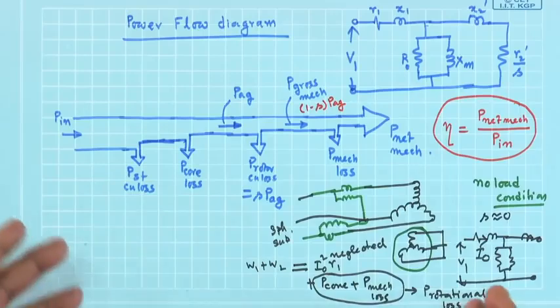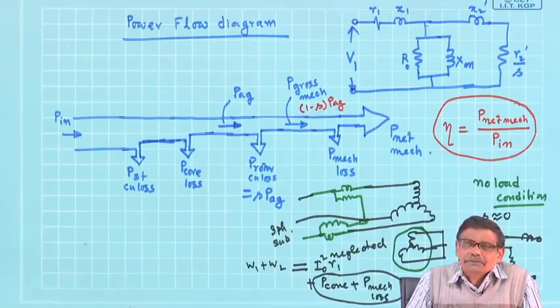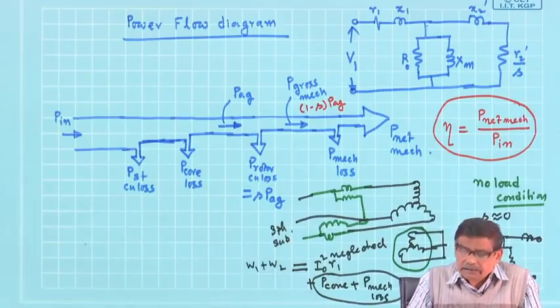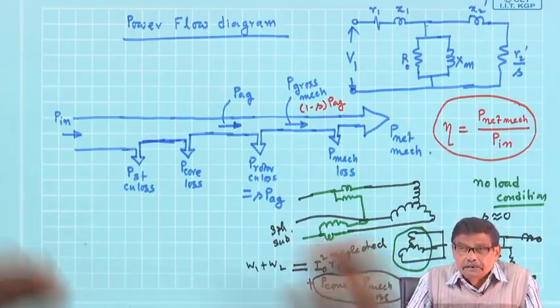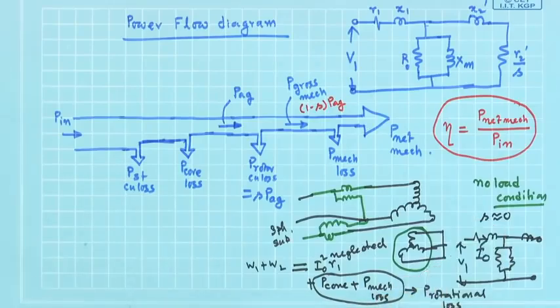But anyway, for an induction motor from no load to full load condition, mind you this statement, what is the change in speed? Very little, 5% slip, a little change, maybe 70-80 RPM from no load to full load. Do you think the frictional loss will change because of this? No, it will practically remain the same, because it is running against air and bearing friction will be similar. Why should there be a difference, because speed variation is less. So frictional loss remains the same.